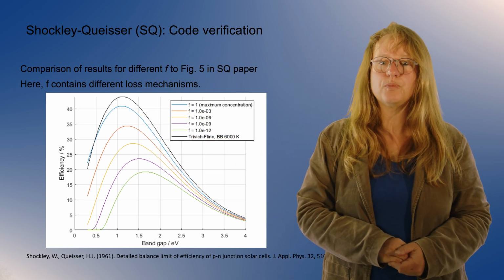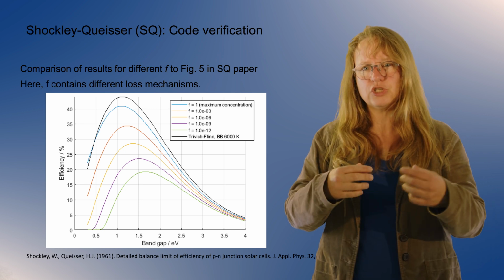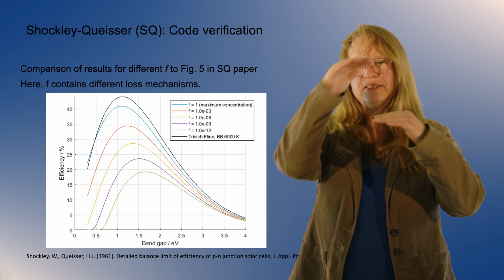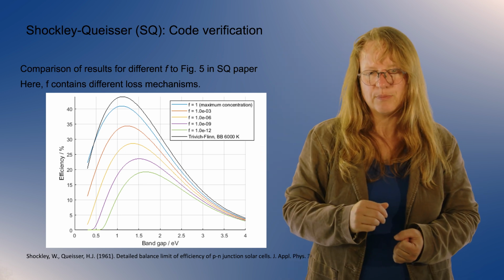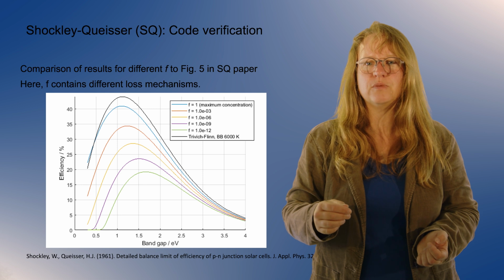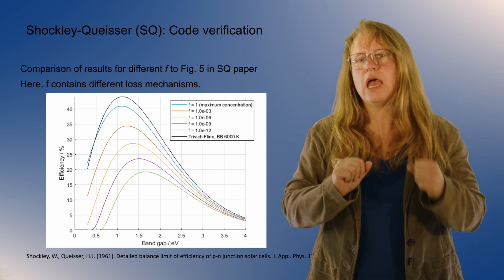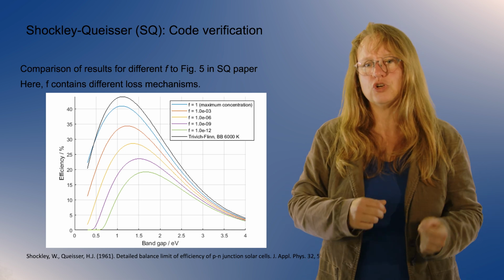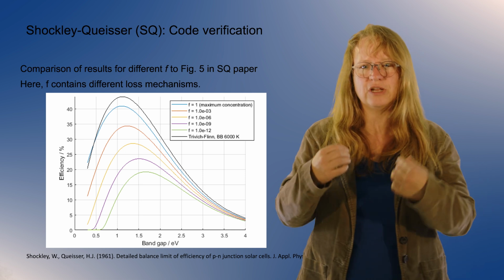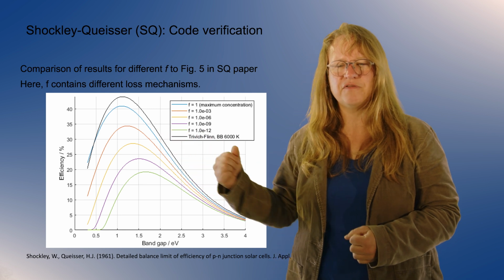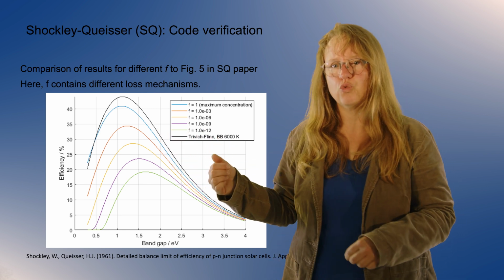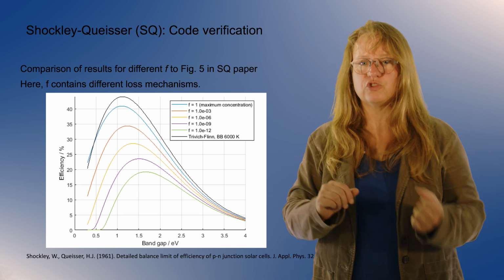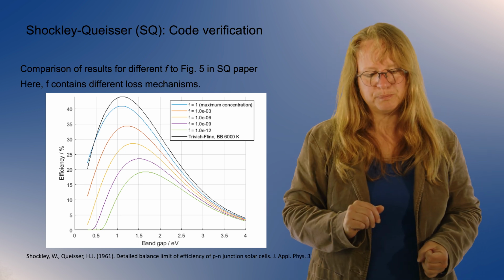And this can be understood by the effect that if the saturation current is getting lower, that means that we get a more square IV shape. And for the Trivich and Flinn efficiency, we just assume that it's ideally square, and we can just multiply the short circuit current with the open circuit voltage and have a fill factor of 100%. And actually, we can see here, if the F is getting closer to 1, this also means that we are getting closer to the ideal of a square situation.